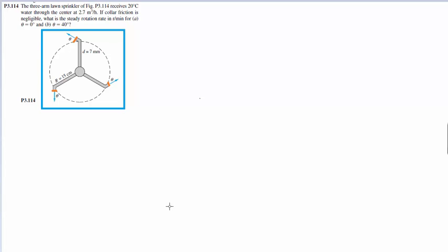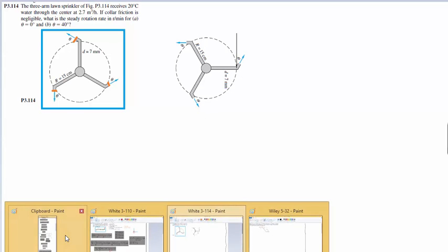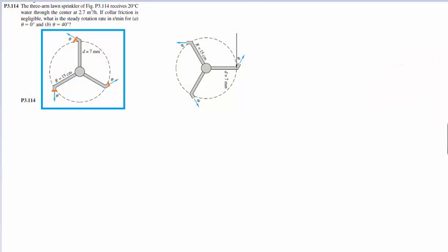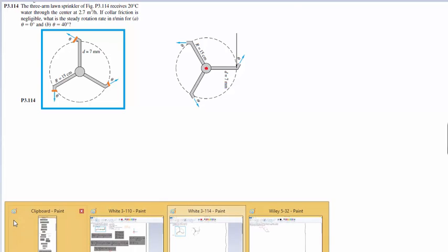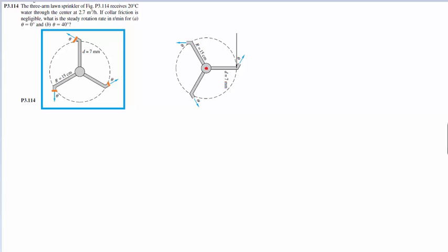Okay, so what else can we do? We could use symmetry to simplify our problem. So again, everything is symmetric to rotation, so how about we turn it so that it looks like this? This will make our vectors a lot easier to write. And we know that this guy and this guy are going to be symmetric to this guy, so we're just going to look at this guy and make everything in regards to him. And in that respect, we should make this right here our point of reference in regards to our torques, because that point is the point of symmetry.